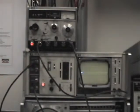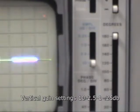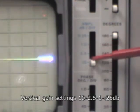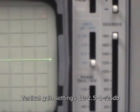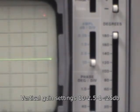It came with a precision power divider and dual insulated BNC cables that were matched very well to each other. That allowed it to make dB measurements down to around 5/100ths of a dB to a 1/10 of a dB very easily. It has a setting over here on the front panel. We have a horizontal gain setting of 10, 5, 1 or quarter dB per division on the screen. At a quarter dB per division, it makes it relatively easy to see changes of 5/100ths of a dB or so.